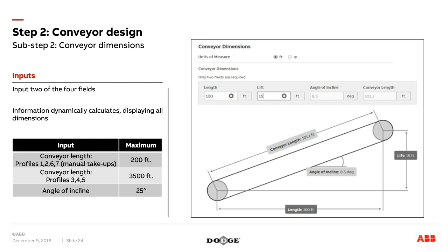Also something to keep in mind as we go through this process, we're doing it for upfront conveyor design, but this is a very useful tool for troubleshooting as well. If you are in situations where an end user is having trouble with a given application, and trying to figure out what's going on, well, a good starting place is working through the actual parameters of what's going on, whether it be tons per hour, and then you put in the conveyor dimensions and the overall speed.